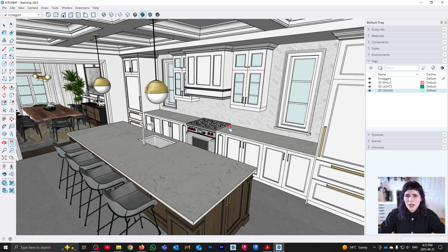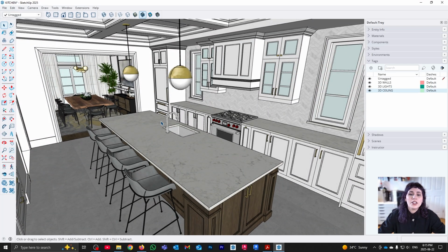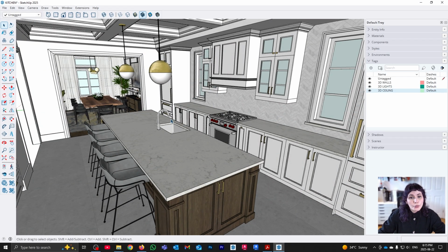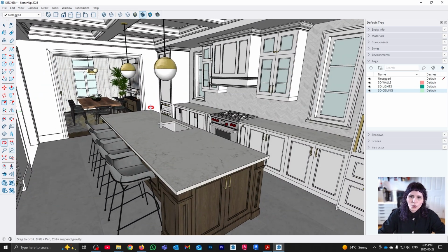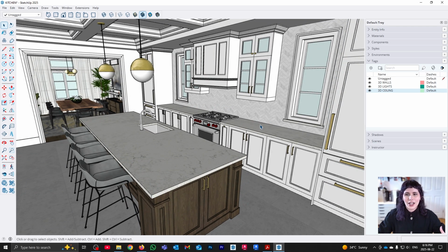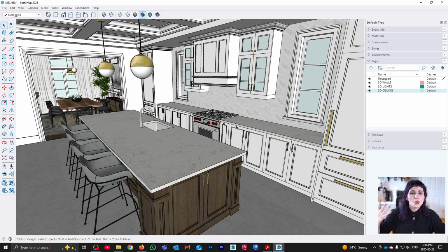So as you can see, we have basically three different options depending on our needs. Perspective, the default, is just the most natural way of looking at the model. It's going to allow us to move around and orbit and model and work with everything that we are doing. Parallel projection is also very useful while you are modeling, but its main purpose is to allow us to annotate 3D objects through the isometric setup. And then finally, the two-point perspective is going to be kind of like our presentation, our final form for our 3D models when we want to show them to other parties.